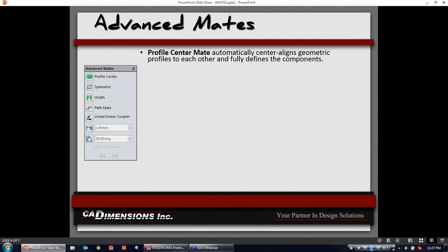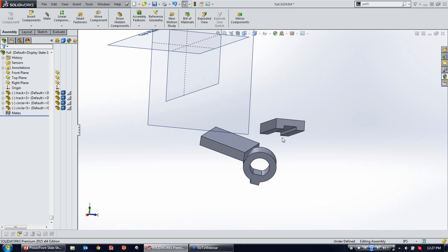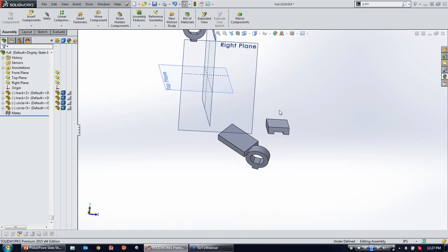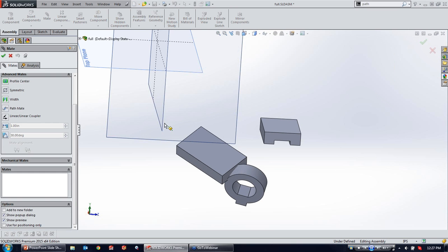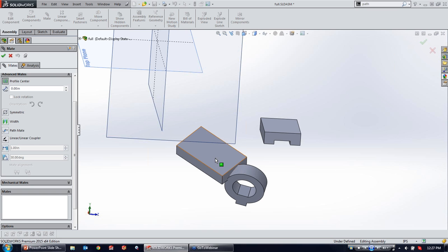a center of mass. So this kind of prohibits any odd-formed shapes, like a U shape wouldn't work here. But we can always make a sketch of a square and use that as our center plane, or our profile center. I'm going to jump back into SolidWorks here. I was showing you coincident earlier, but I'm just going to show you a quick way to mate two squares in this instance using our profile center. So I want this base and this base.